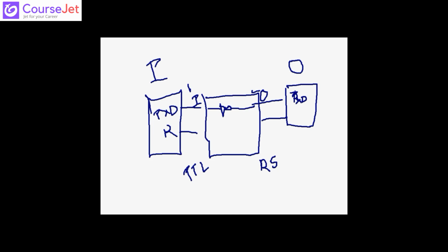Now, as I said, coming to your baud rate. Here comes the logic of using the 11.0592 megahertz crystal oscillator. You have some predefined baud rates already available, something like 9600. 4800, just divide it by 2. And if you want to go up, you multiply it by 2, 9600 into 2.